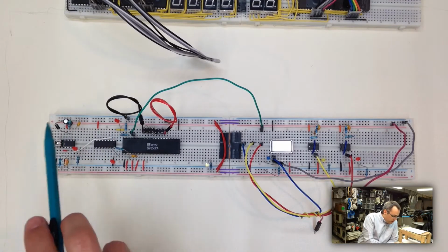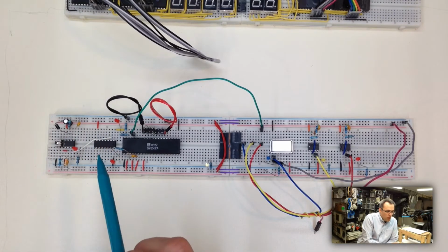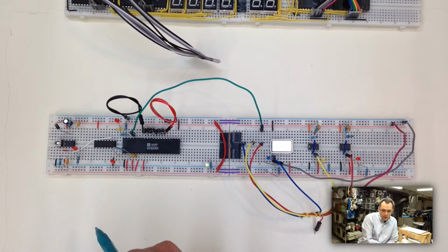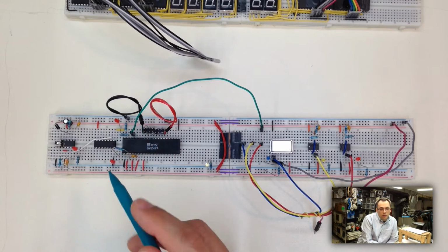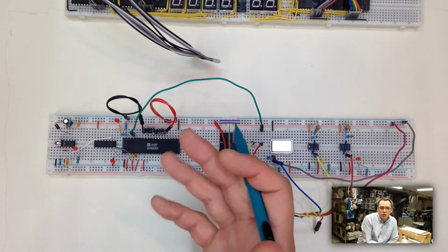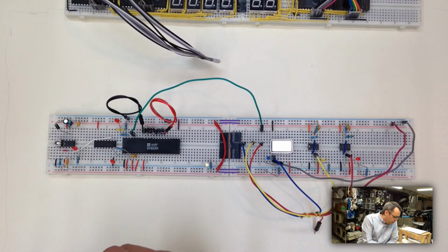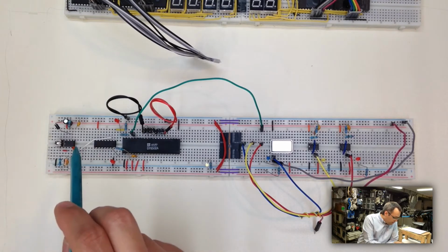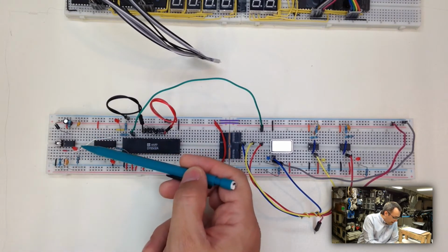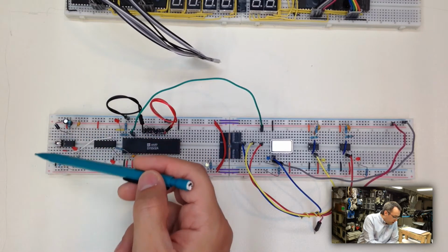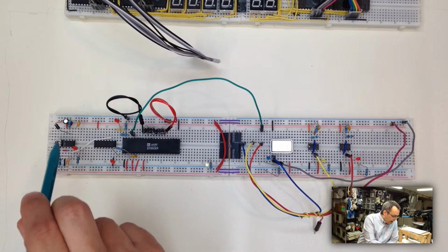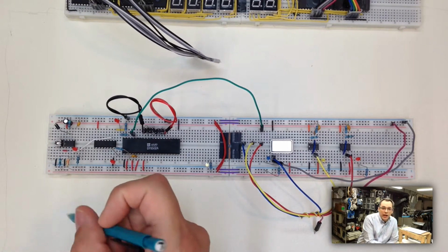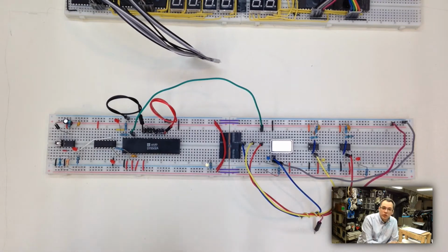The reset circuit I used here is similar to the one that's in the JCM-1 computer. It's also similar to the reset circuit that's on the floppy controller of a Disk II in an Apple II. It's pretty straightforward. Nothing super complicated there. I did add one little thing to the reset circuit here, and that is this little LED. This allows me to visualize what the reset circuit is doing. So when that pulses output, that LED will light up, and I can see an actual reset pulse is being pushed out to the system.